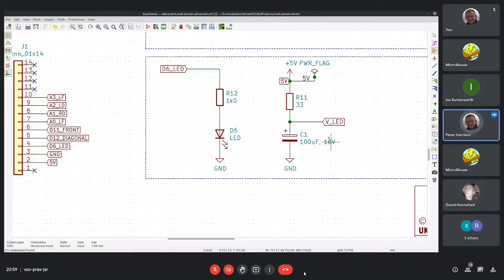It's quite possible you can skip the netlist generation, and it's possible that in version 6 it gets skipped. All these various steps are not things that you have to do in Eagle, and the reason for talking about them tonight is to point out that it is different, and it may seem like a bit of a pain to have to do these various things when in Eagle you just click on board and away you go.